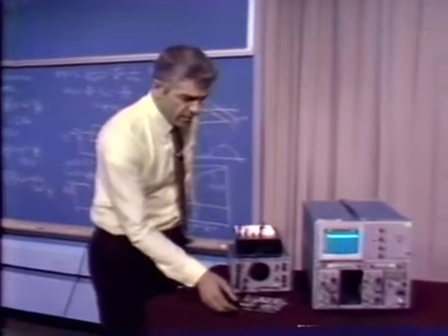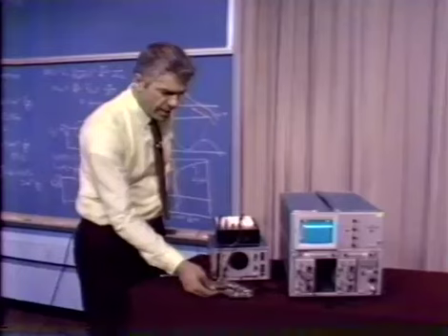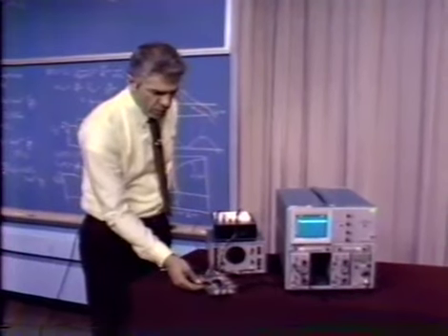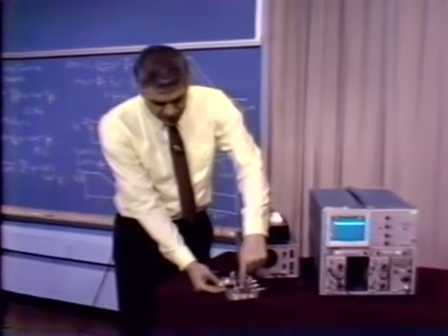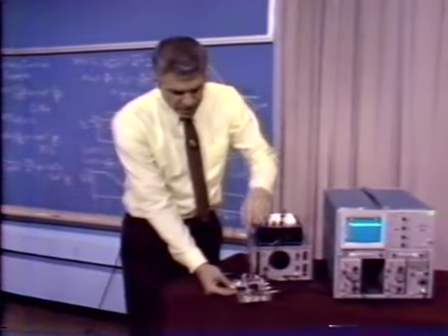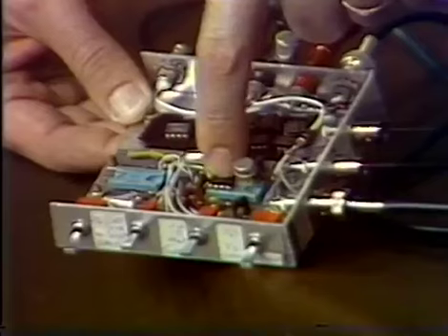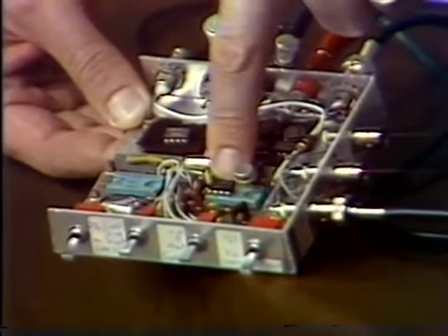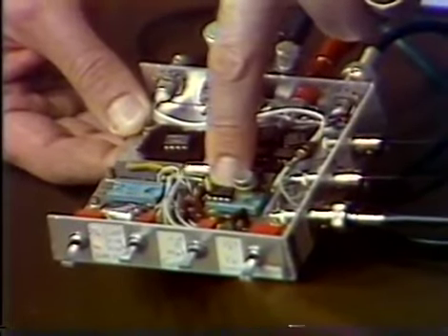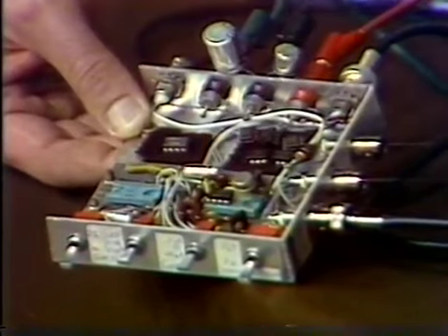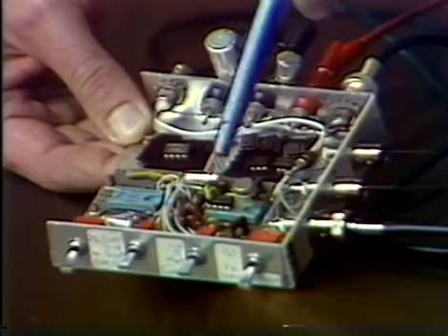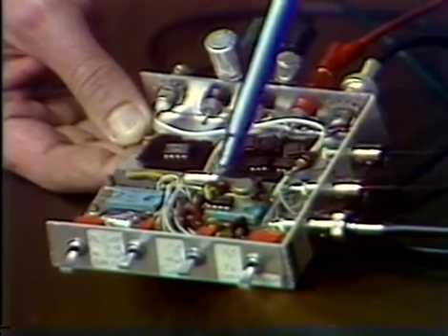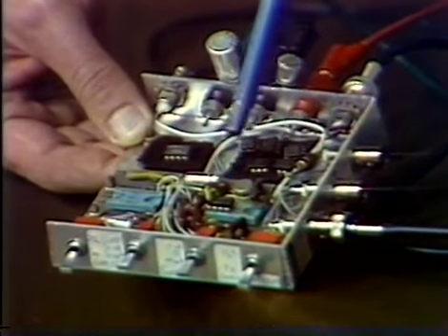Here, once again, we have the test vehicle that we have used so often. We have our operational amplifier. In this case, we have the ability to compensate this operational amplifier either with 1 over s single pole or with two-pole compensation. We have a buffer amplifier. If you recall, we used this same configuration before when we were looking at 1 over s compensation.